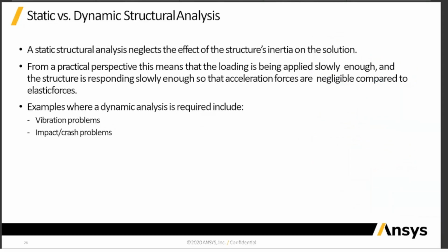Then another way of solving the structural analysis is a dynamic approach. Static structural analysis neglects the effects of the structure's inertia on the solution. So inertial loads are not considered whenever you are doing a static structural analysis.